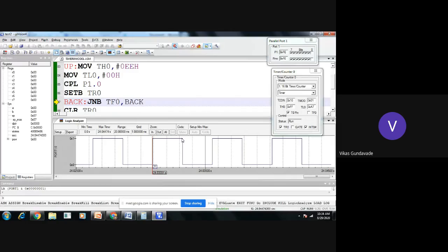Okay, so everyone got it. So this is the way of writing the program. While you are writing the program in assembly language or in embedded sim, to check the status of the timer, just click on peripherals, open the port to check the event, then again click on peripherals, open the timer counter module, and after that you can execute the program. Now this is one way of writing the program.